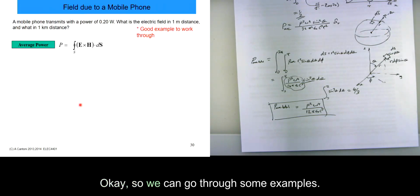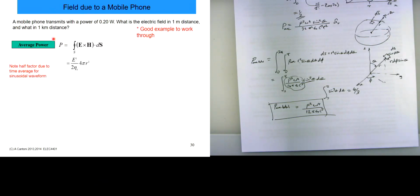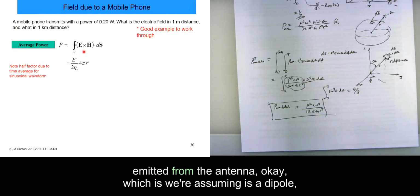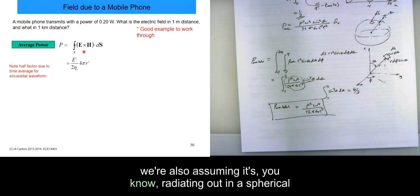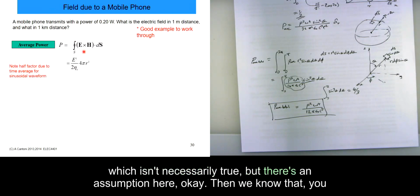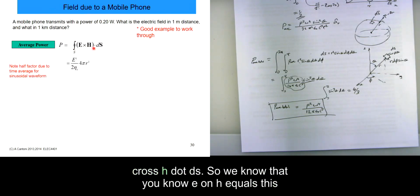Okay, so we can go through some examples. Say a mobile phone transmits with a power of 0.2 watts. What is the electric field at 1 meter distance, and what is it at 1 kilometer distance? We know that the average power emitted from the antenna, which we're assuming is a dipole radiating out in a spherical pattern, so that radiation is equal in all directions, which isn't necessarily true, but it's an assumption here, is going to be the time average of E cross H dot dS.